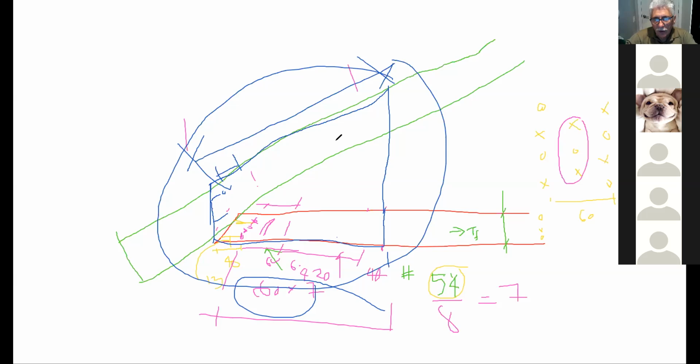Okay. Is that okay? Yeah, but in other words, you don't work this out and then all of a sudden you make a gusset plate go like that. You just go straight up and then you come down. I mean, this piece of plywood that you're saving is going to get scrapped anyways. It's just going to end up in the wood pile. So what you're trying to do is determine this length here so that you can cut this piece out of your plywood and get your gusset plate out.